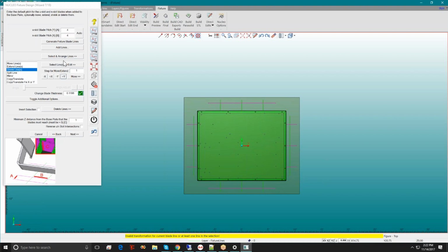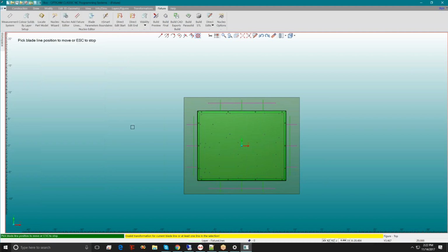The other way you can do it is you can select and arrange lines, which sometimes is good. You just say, give me like 8 in X, 8 in Y, and then you can just go in here and select and arrange. You just go around in a loop. You say, okay, this one, let's do this one. This one, I want to move to, say, the end of there, right? Then this one, I want to move to mid end of there. So you go around in a circle, looping around, just moving things to snap positions, right?